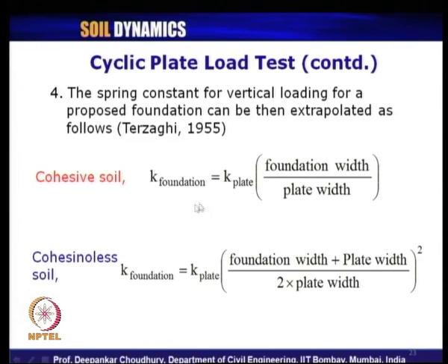So, in this manner we can easily find out the stiffness of our foundation to be designed, and then using this value we can further do our dynamic analysis, because in all our dynamic analysis we need this value of spring constant. That is one of the basic inputs we require. So, this is the way, in a simplified manner, we can compute the stiffness of the foundation.